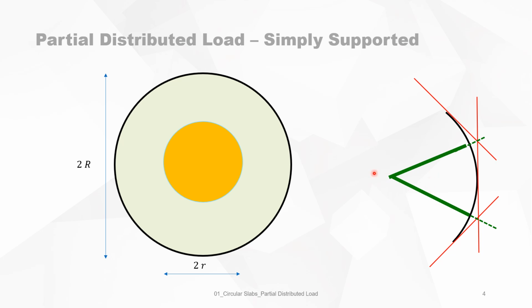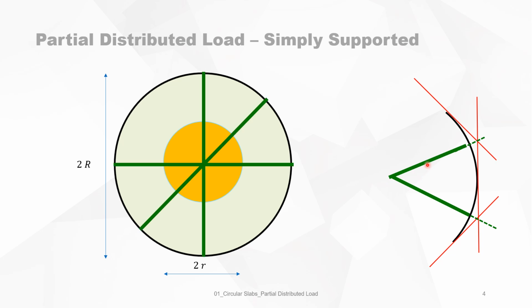Then we can draw the 2 yield lines. So we'll use this principle for the whole circumference, and we draw not all, because that's not possible, but some of the yield lines. So there you go. Now I've taken a couple of yield lines, and it's always the same mechanism. The axis of rotation is a straight line at one point of the circle, and we have in total an infinite number of yield lines.